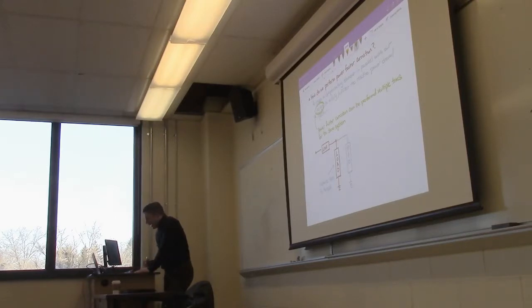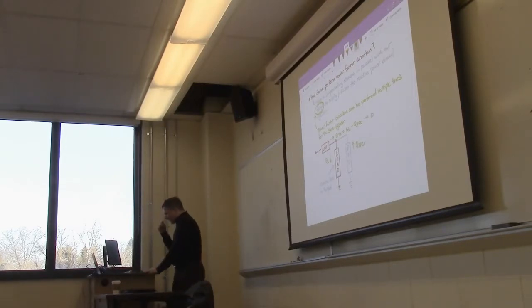So therefore, what we have is we'll have a value of QL that'll be consumed. We'll have a value of QPFC that is being injected. And then we'll have a value of Q transmission line, which will be equal to QL minus QPFC, which could be equal to 0 if we design everything correctly, right? Obviously, the sizing needs to be done right.